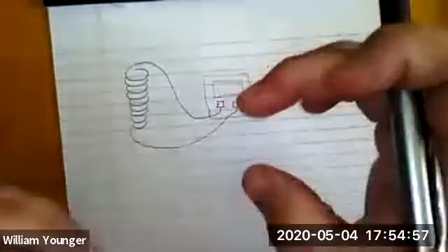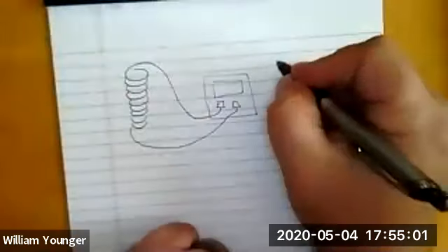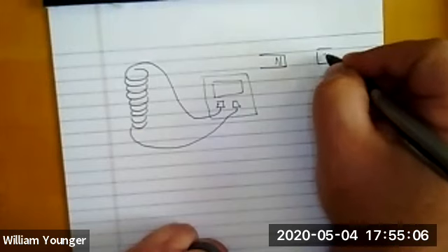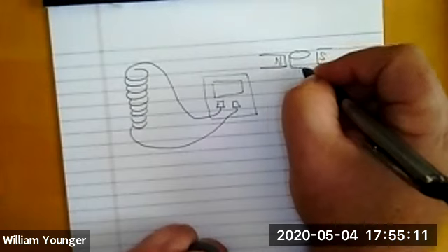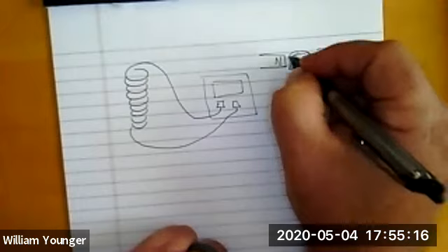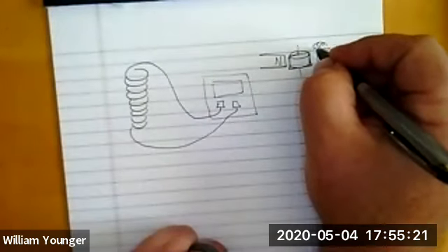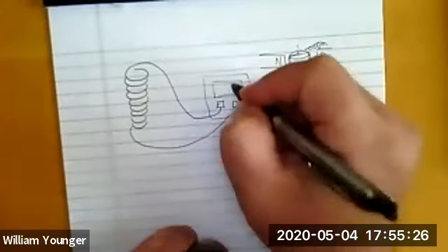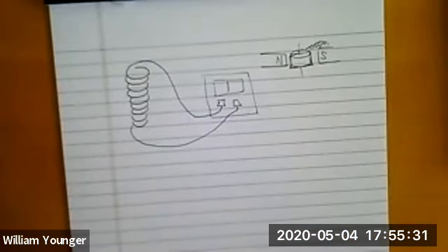That coil that's wrapped around the iron is in between the north end and the south end of a magnet. So I have a north end of a magnet, and a south end of a magnet here, and a chunk of metal that has a coil of wire wrapped around it. Now it's on an axis so it can spin, but it's also connected with a spring so it can lock it in one particular spot. Normally, that spring keeps the needle pointing straight up and straight down.